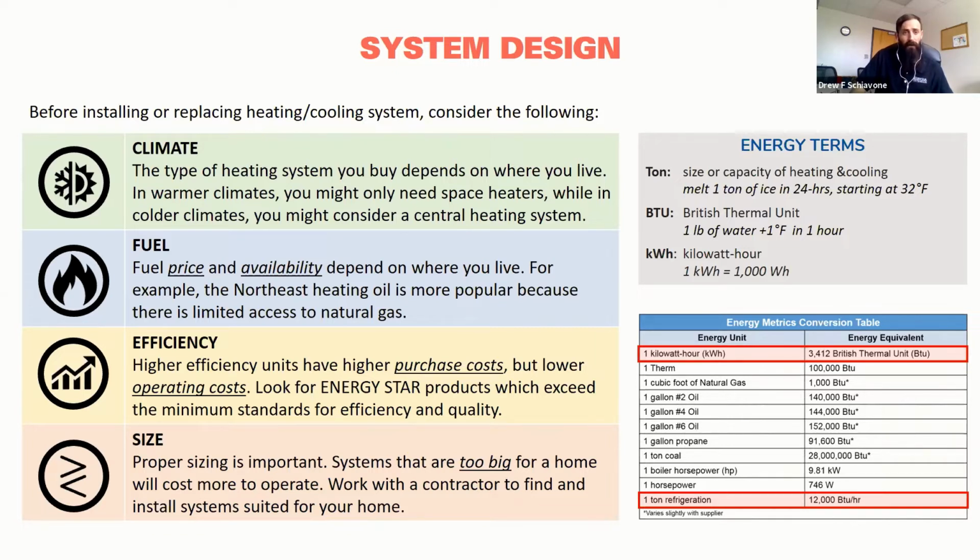But we're really going to talk a lot right now about the efficiency ratings for all of the different types of systems, as well as proper sizing. If the system's too small, it's not going to meet our demand. With a hot water system, for instance, if it's too small, you're not going to have enough heat for your shower. If it's too big, it's not going to be as efficient. So we're going to look at some parameters there.